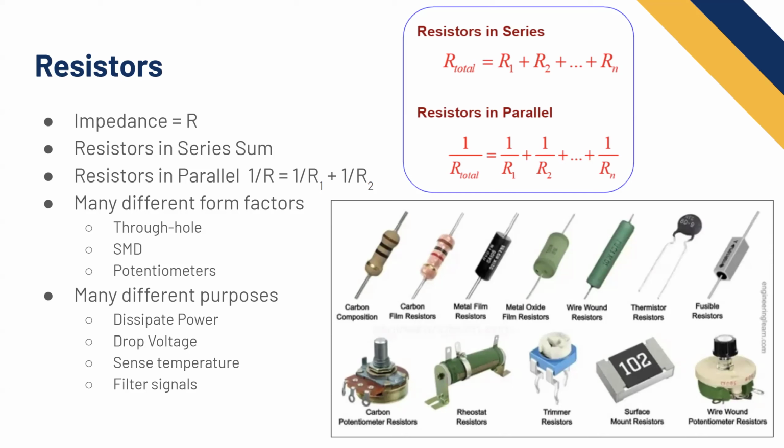They come in many different form factors, so I just put a photo of a lot of them on here. A lot of the stuff that I'm saying, you're going to hear once, and then you're going to keep hearing it for the next 4 years as you go through school. Resistors, you're going to see a bunch of different form factors, like through hole, which is what a lot of these ones on the top are. It's like a wire, and it goes through a hole in your PCB. Or SMD, which is surface mount device. Sometimes you see SMT, surface mount technology. They refer to generally the same thing.